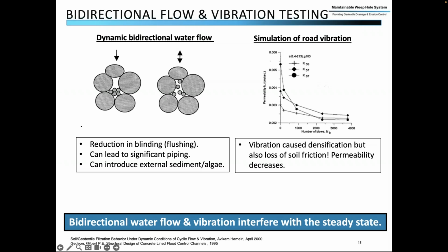All those little vibrations will disrupt the backfill and cause the drainage performance to decrease. So especially with abutments, you've got massive, very strong structures, but water will build up quicker behind those structures over time as road vibration disrupts their drainage system.